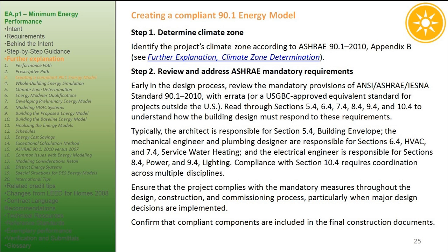Typically, the architect is responsible for section 5.4, building envelope. The mechanical engineer and plumbing designer are responsible for sections 6.4, HVAC, and 7.4, service water heating, and the electrical engineer is responsible for sections 8.4, power, and 9.4, lighting. Compliance with section 10.4 requires coordination across multiple disciplines.